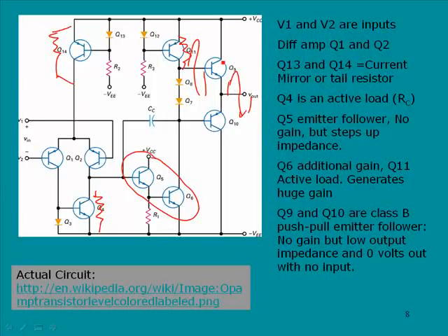And the advantage of this kind of configuration is that the output here can be set for 0 volts. Now remember that we have the positive and the negative voltages in an op-amp, and so if we had, say, positive 15 here and negative 15 here, the output, at least in theory, could swing from positive 15 to negative 15.